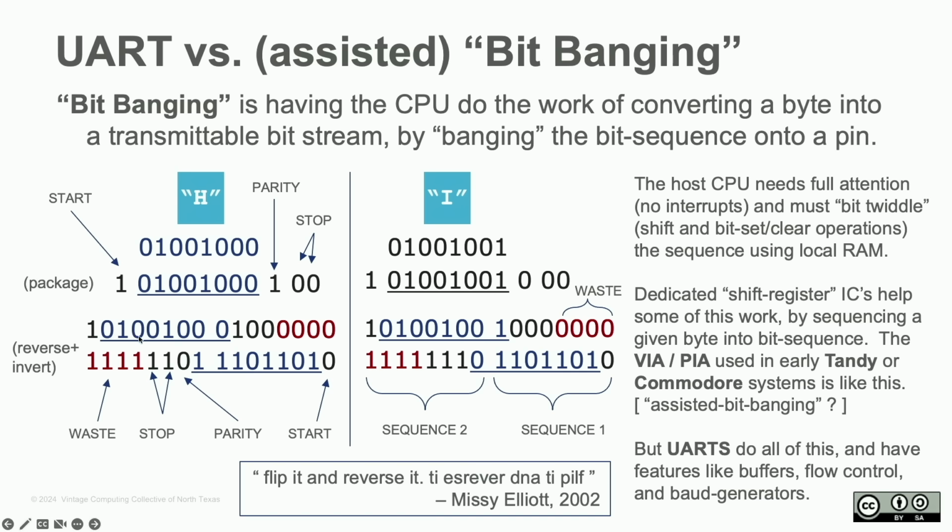Down here, yeah, that song, Missy Elliott, you gotta flip it and reverse it. That always gets in my head when I'm talking about bit banging. You have to reverse the order that's going out and flip the bits. So there's that concept of bit banging.